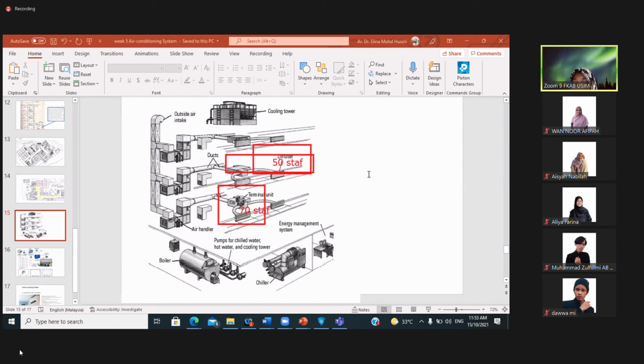So when you do the calculation on thermal comfort, one horsepower of split unit or aircon will cater the comfort of only how many people? Only 5? So when you divide 70, you need 10 split units. So where do you want to allocate them? That's why I'm telling you, this is not so efficient. You need the whole thing to be operated as one building, easy to generalize and easy to disperse the air conditioning rather than using split units.